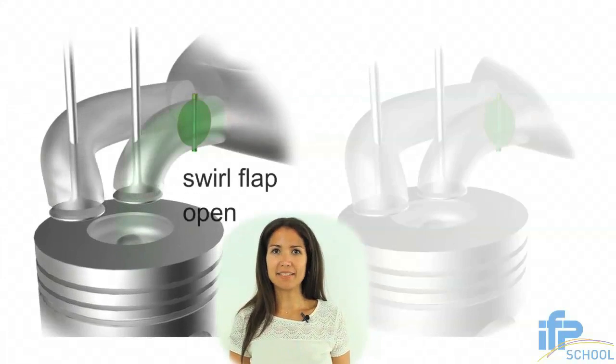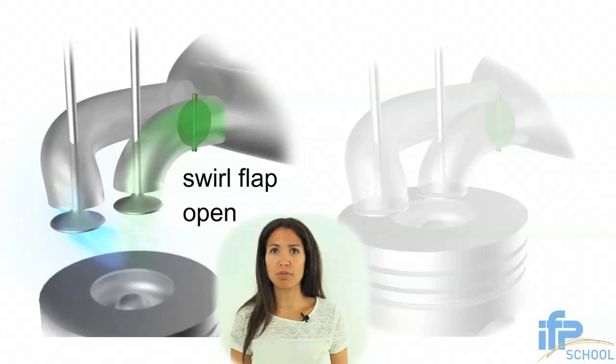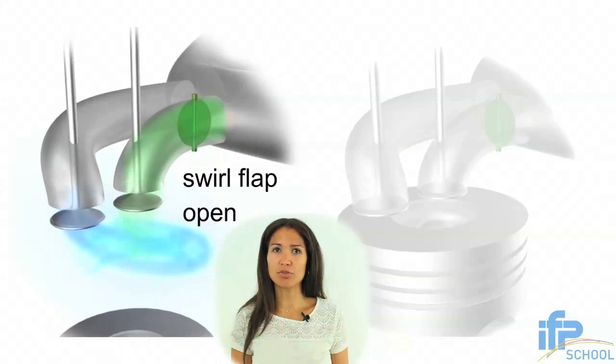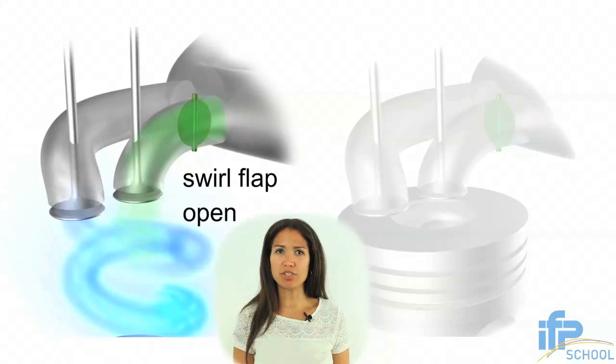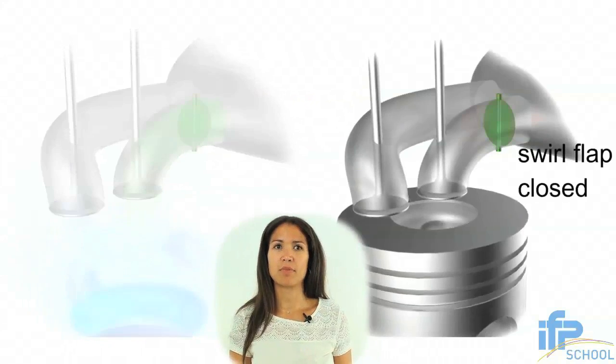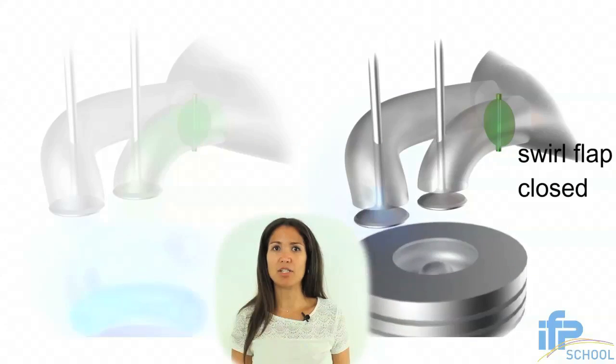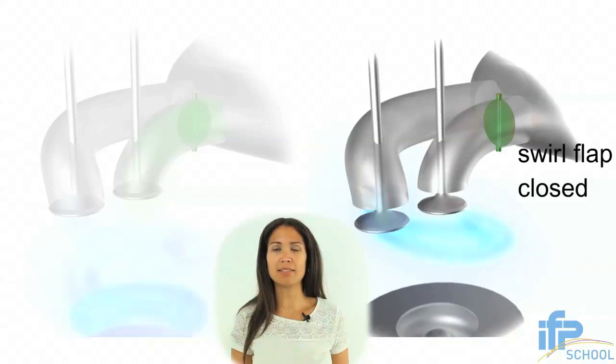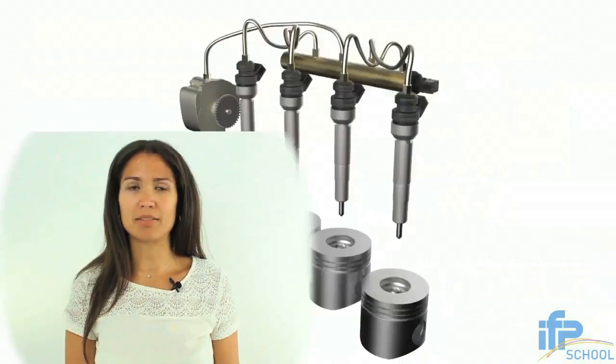The air goes then into the intake manifold, which distributes the air into each cylinder of the engine through the cylinder head. Here we need to separate diesel engines from gasoline engines. In diesel engines, the intake manifold is equipped with swirl flaps, which are used to regulate the inflow of air in order to achieve optimal combustion. The swirl movement is also given by the shape of the intake pipes inside the cylinder head. This is also called internal aerodynamics.